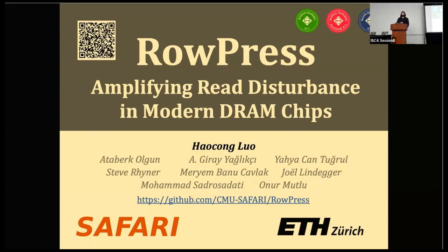Okay. Questions? Was it just me, or did they say the average improvement was negative? Like the average performance penalty was negative? That's because we evaluate multi-program workloads, and the metric is weighted speedup, and because we limit the maximum time that the row can stay open, it improves the fairness in some workloads. Okay. So that causes the average slowdown to be negative.